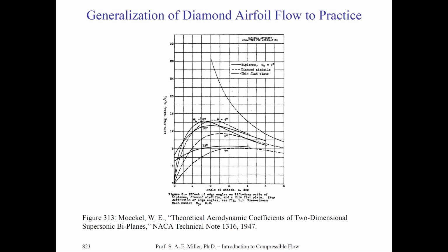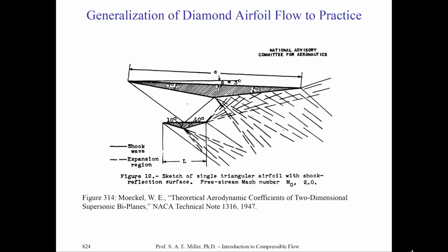And that's excellent. And so you can see, we might be able to construct this supersonic biplane to achieve really optimal lift and drag ratios, which is always good at very small angles of attack. Now let's do a thought experiment and take the lower triangle from the diamond airfoil, split it, flip it over on its x-axis, make it smaller, and move it forward.